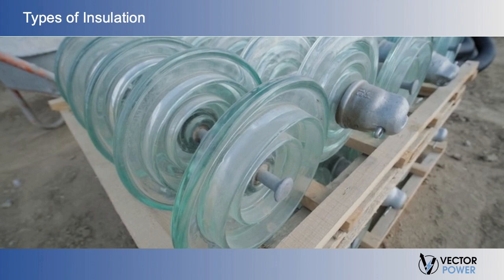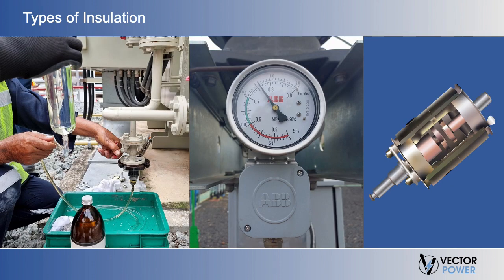These rigid structures must be shock resistant, be relatively water impervious, and be able to endure corona discharges over their surfaces. Liquids, gases, and vacuums are all fluid insulation. For all of these, the electrical structure must contain the fluid in regions of high electric stress. Fluid insulators are used in very high power, high current devices where solid insulation and a heat sink would be too bulky, or where a very large amount of waste heat must be removed from a relatively small area.